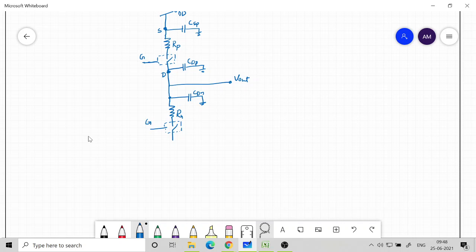It is controlled by the gate. Then the other side I have one more capacitor which is CSN, and then this is ground. Okay, so I replaced the two transistors NMOS and PMOS with their corresponding RC equivalent circuit in order to get my inverter RC. So now this is both connected together, and that's where I give my input.